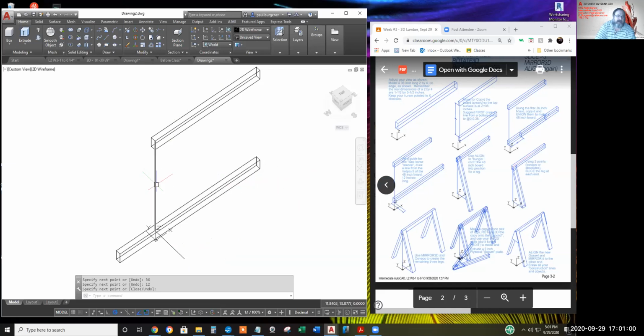So it turns out I needed the construction line of step 1 to begin with to follow the rest of the steps of the handout. Again, drop down, click a line, select the 48, enter. Bungee cord from there to there, bungee cord from there to the midpoint of the proper edge. And now which corner do I select to bungee cord to this chalk line? You know, either one will work, but the feet of the Sawhorse will be slightly different by the width of the 2x4.